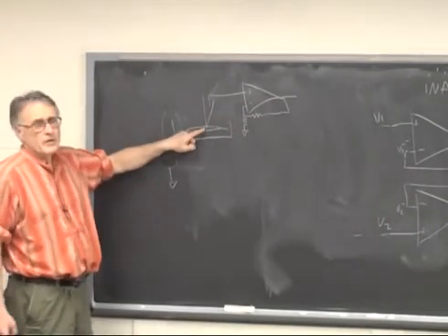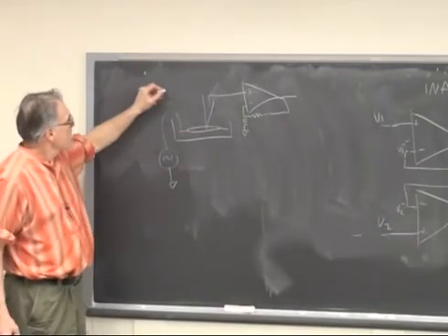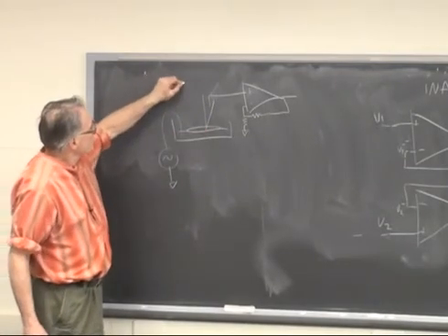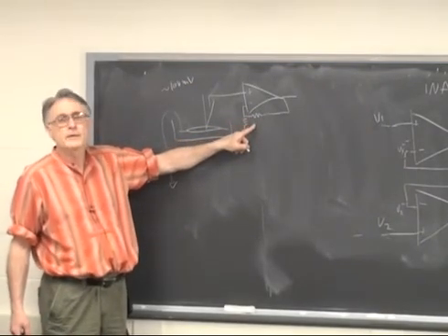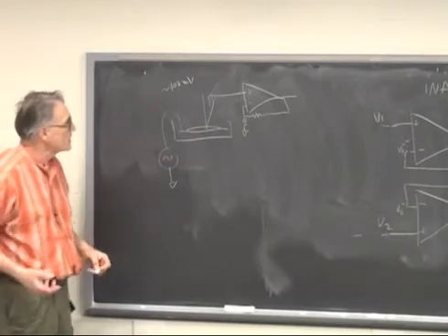If you're intracellular, if you're actually getting an electrode intracellular, the voltage changes are going to be on the order of 100 millivolts. So the gain doesn't have to be awfully high here. It might be a factor of 10 to get it up into the kind of volt range.